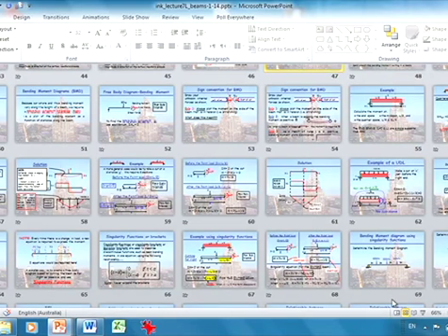Yeah, because I mean, so if it goes down like that, and there's a reaction, that your middle? No, it's this one. Wouldn't that be W2? Oh, at the end, yeah. Okay, so let's call these P, P. So in this case, my total reaction is 1, 2, 3, 4, 5 P. So these reactions here are 2.5 P each, and that's 2.5 P each.